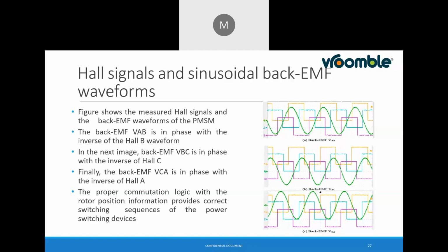Now, the MOSFETs will keep on continuously switching on and off based on the given sequence, and there will be an overlap of two phases because you need to continuously rotate the motor, right? But it has to be a very smooth and precise one. So the sensors will continuously detect your speed. It will give the feedback to the controller on which phase has to be energized one by one.